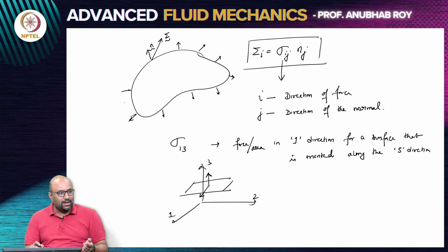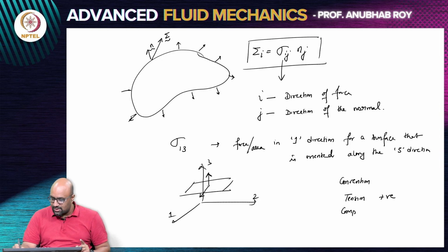That is what would happen if your surface force was always aligned with the normal. So, the sign that we always say is that this is a convention. The convention that we follow is, if the force is aligned with the normal, which is tension, then it is positive. If the force is opposite to the outward normal, then it is compressive and it is negative.